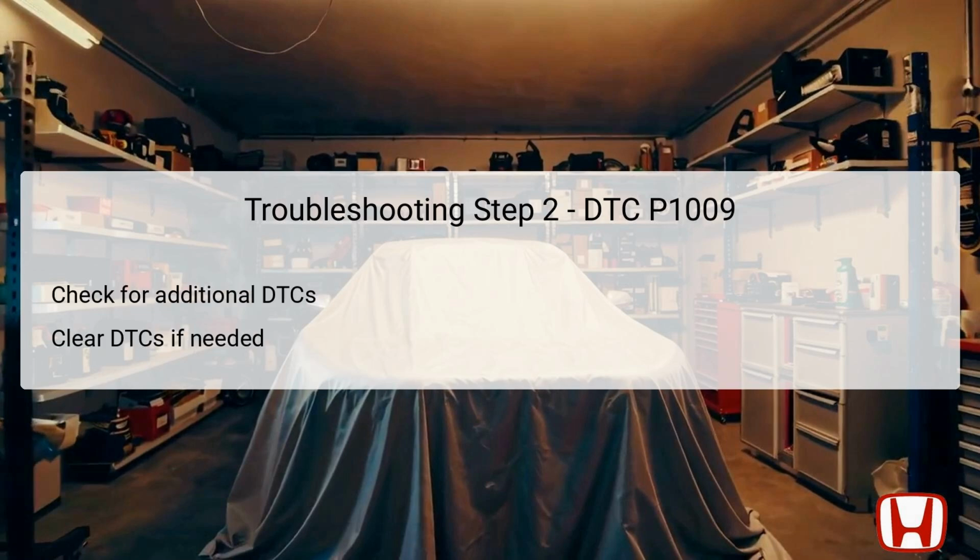In Step 2 of troubleshooting, it's essential to check for any additional diagnostic trouble codes present. Often, a single issue may be accompanied by other codes that can provide a well-rounded view of the vehicle's current state. If any active codes such as P0335, P0339, P0340, P0341, or P0344 are detected, they should be addressed prior to focusing solely on P1009, as they may point to related faults in the timing or sensor systems.